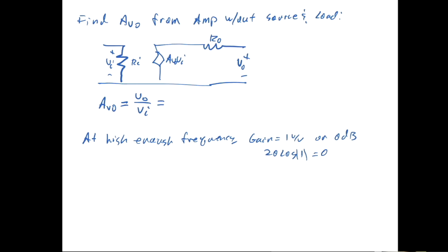Yeah, there will be some frequency. At some very high frequency, we call it the 0 dB frequency, or we have some other names for it, resonant frequency and some other things. The gain will actually be 1, and at even higher frequencies, it'll be a fraction.